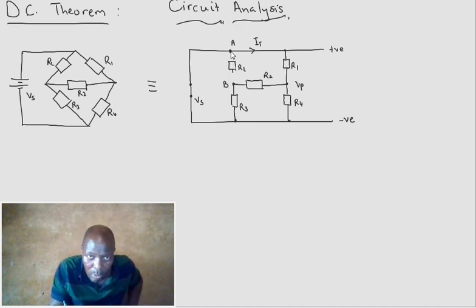Now we must run from A to B, and see what the resistance between those two points is. So I always want to start with a straight line and say this is my A. From A, I've got two. This whole line is now A. If you notice, I've got one way of leaving A, and that way is through R1.